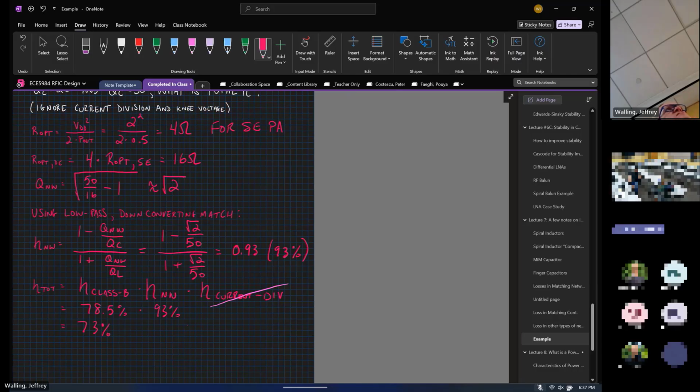And one thing you might notice is that the differential amplifier gave us quite a big advantage there. We didn't talk about why, but we don't want to make very large impedance transformations. If we make large impedance transformations, that means that the network quality factor ends up being big, and having a big network quality factor with lossy components hurts us. So we'd like to keep the network quality factor as low as we can. Practically, a differential amplifier is a good way to do that.